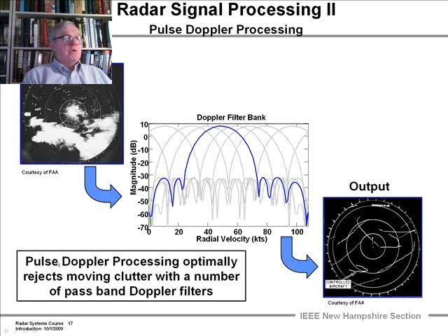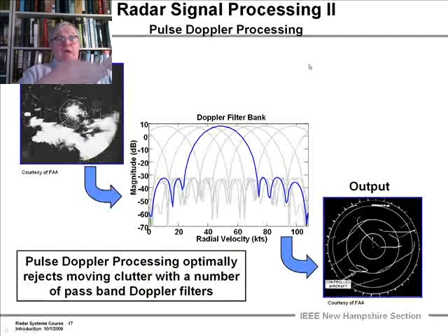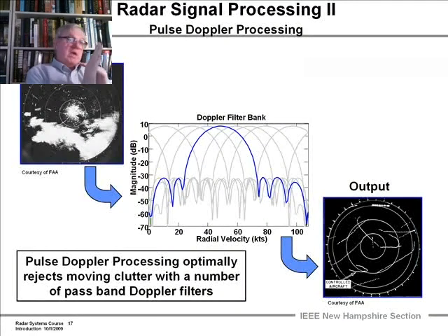So what we wanted to do, what was developed, was using a large number of pulses, the order of 10, process them through a linear filter, and get out a whole series of passband filters. Those 10 backscattered at the same range gate are passed through a set of weights which have a frequency response that of a passband filter or a transversal filter, which has this characteristic.